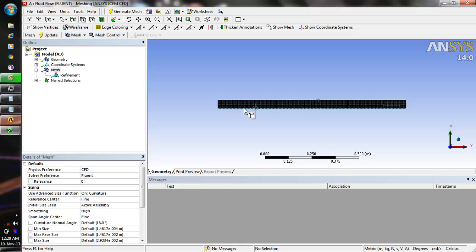The fluid layer near the hot wall will get heated up and become less dense, so it will rise up due to buoyancy effect and touch the cold wall. Again it will get colder and become a bit dense and it will come down. So there will be circulations observed in this diagram. So this is the flow physics.